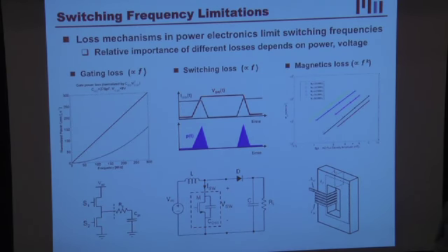We have semiconductor switches. To give you an example, every time I turn a switch on or off, I am going between current and no voltage and voltage and no current in the switch, but right when I transition between the two, I tend to get some overlap, and that causes bursts of power dissipation, a loss mechanism proportional to frequency.